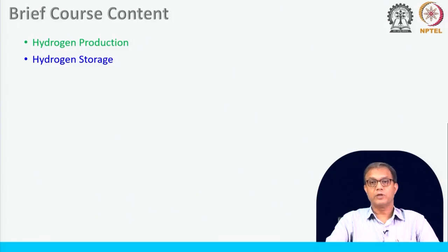So, its storage, its liquefaction process is completely different from the other refrigeration processes. So, we will look into that cryogenic liquefaction process, and then there are other storage means like storing hydrogen in metal hydride, cryosorption storage, then cryocompressed hydrogen. Those are all futuristic methods, and we will try to look into them from their utilization point of view.